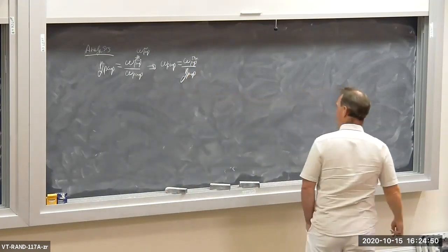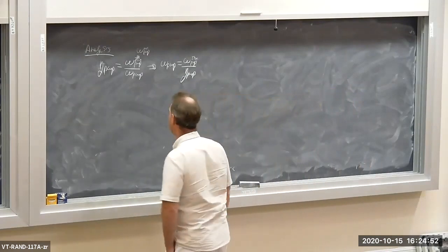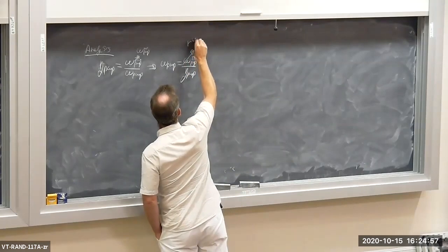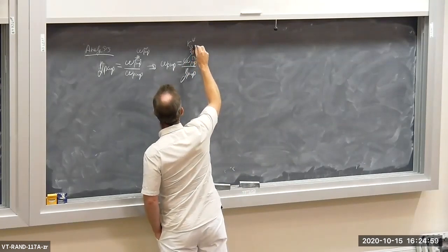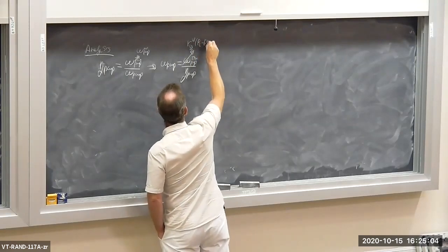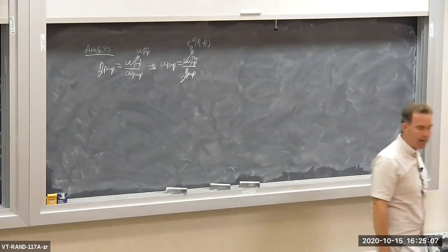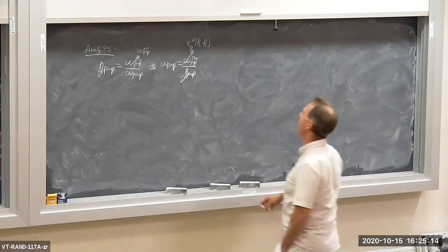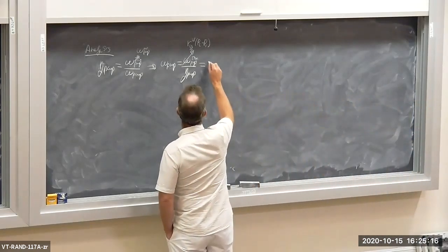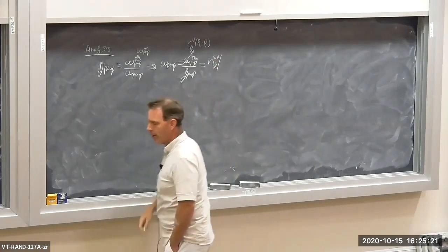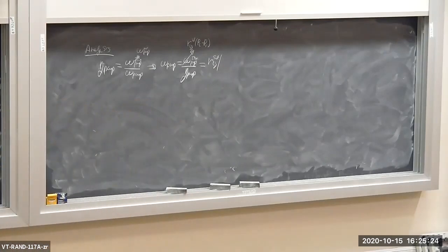Okay, now we already have an expression for isentropic efficiency for the pump. So we developed this last time. That's the specific volume of the saturated liquid times the delta P. So that'll be P2 minus P1. We developed that expression for isentropic or reversible pump work, if you like. So I have a specific volume of the saturated liquid. Let's see here, that's going to be evaluated at a pressure P1.